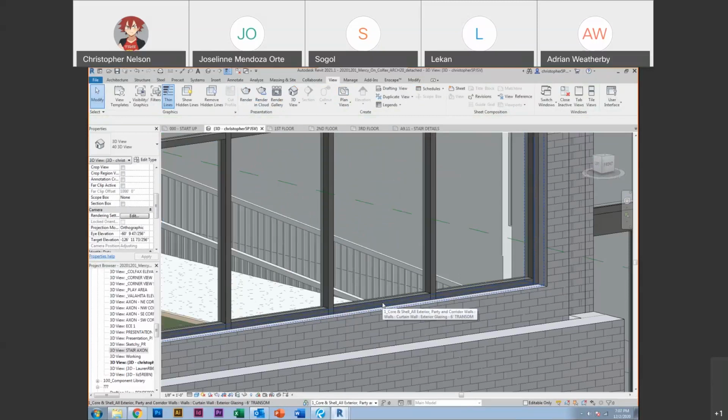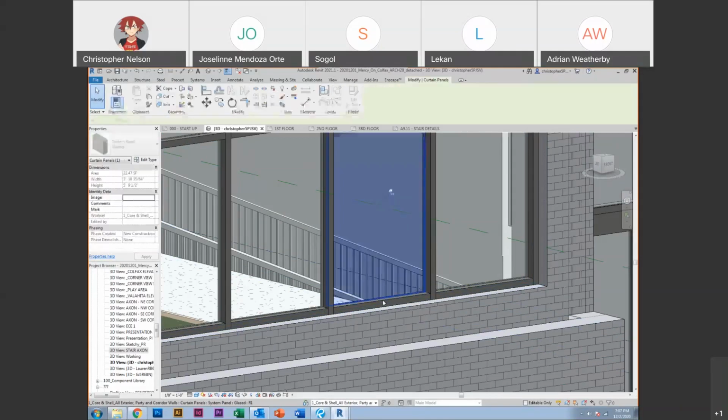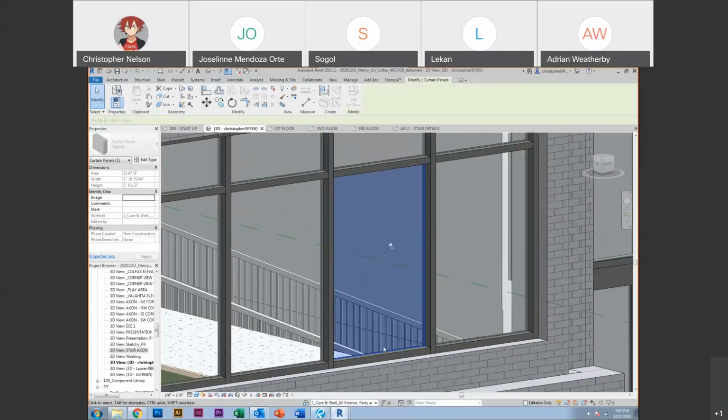If you just zoom in, you hover over the mullion and the glass, some corner is usually what I would try to do. And you press tab. First I get the mullion. I get a few things in space, but eventually I'll tab and I'll get the glass where you have this rectangle of blue. Right, so I have that.